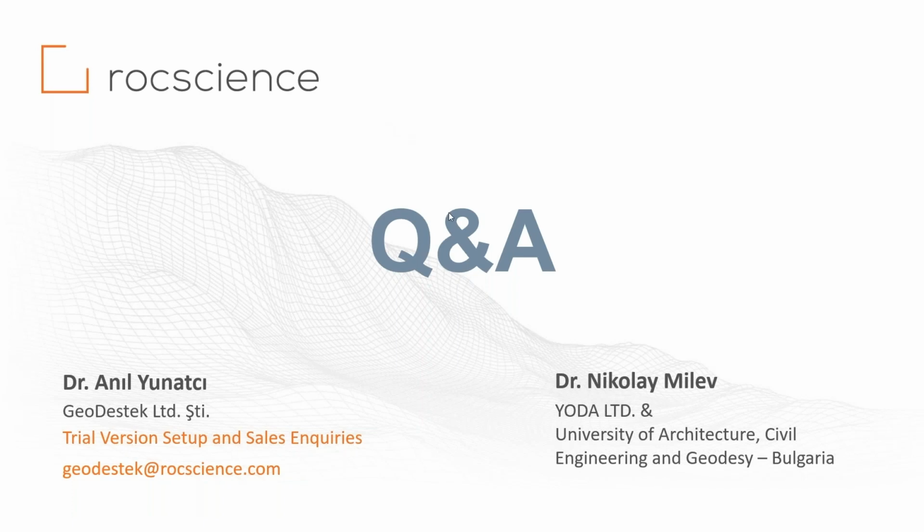Another question: how much settlement is good for a structure? Once again, codes would give you the limits, or some special requirements would give you the limits. In our case, limitation of tilt and settlement was given by the client, but if you do not have such information in some cases, you could probably stick with what is given in the codes.